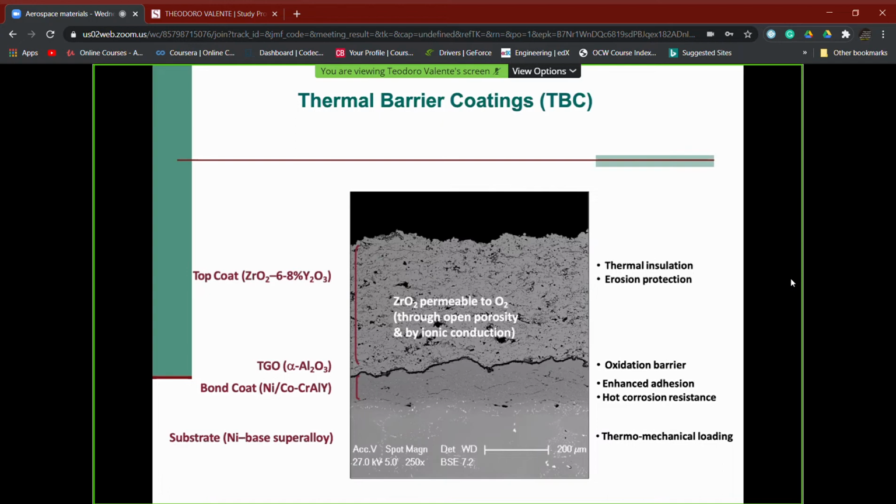We have the classes of ceramic materials, the oxide-based ceramics and the non-oxide-based ceramics. If we use a non-oxide-based ceramic working in an oxidizing environment, that means with oxygen inside, at high temperature, the non-oxide materials will experience an oxidation phenomenon, high temperature corrosion.